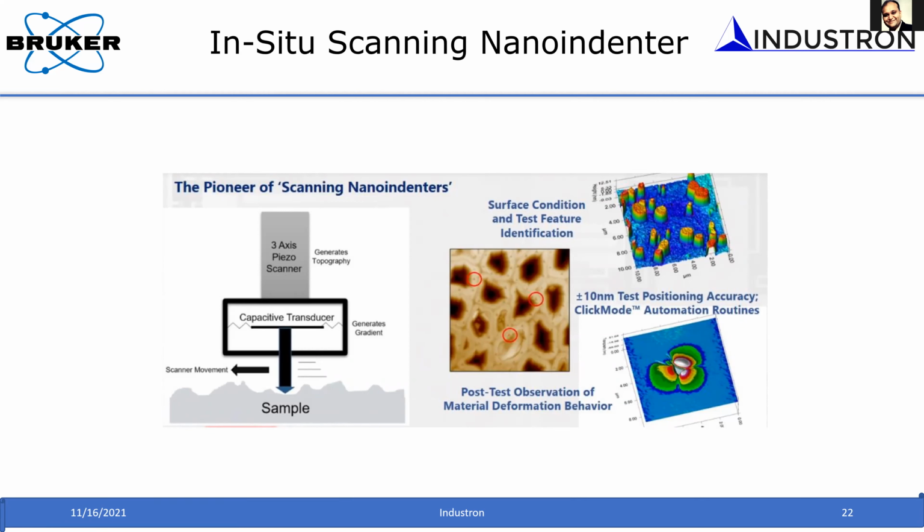But you can do almost like 1 micron by 1 micron scale. You can routinely do, depending upon the tip dimension, for example, maybe 20 to 30 nanometers, the resolution is going to be limited. Within that resolution, you can do very high resolution imaging with this in-situ SPM imaging.